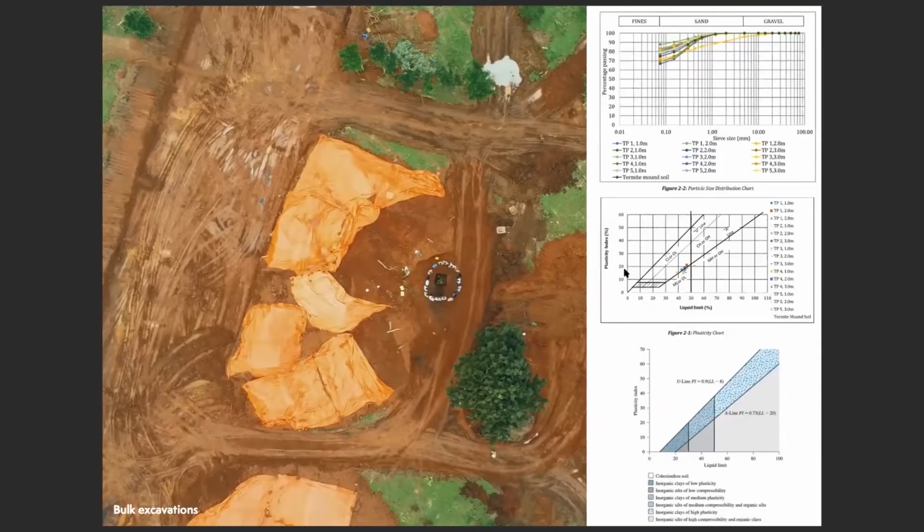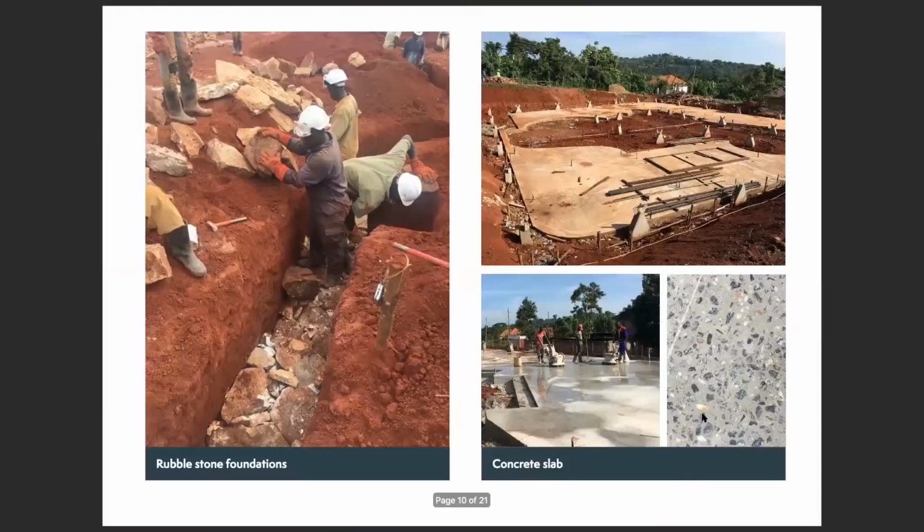And the other important part about soil is the consistency, which is the plasticity indices, which is basically how well this soil can hold together. And for our part, our soil was a bit on the line, which really tends between clay and silt. It wasn't really very good. And that's why, you'll see later, we are blending this soil to make it a bit more suitable.